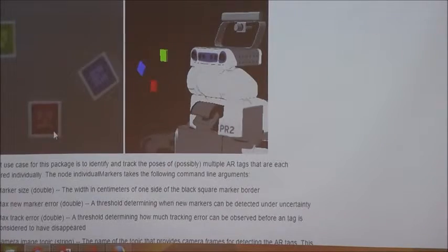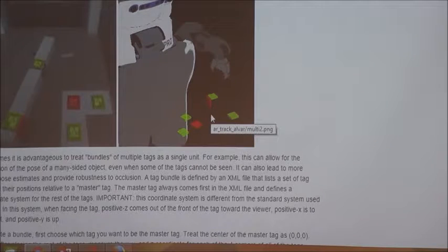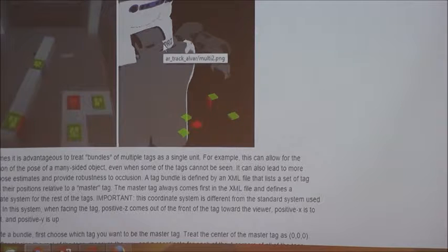Okay, so these little tags can be detected with just about any camera, as long as you have some special nodes set up to allow for calibration of your camera. So you can detect the tags in different positions, and the best part is it tells you in 3D space how they actually look. So if you need to detect something in a certain pose, you can use these tags. This particular robot is a PR2 made by Willow Garage, which is basically the same group that started ROS, and everybody else kind of contributed, made it better, and really enhanced it in many different ways.